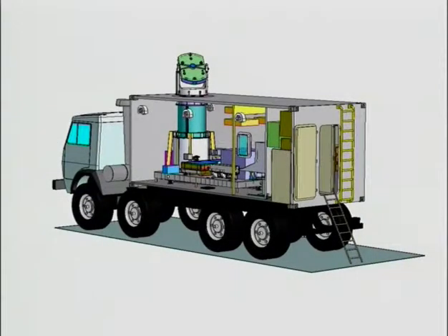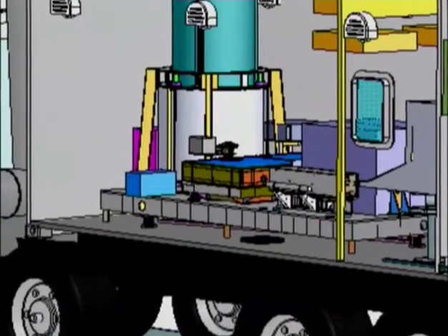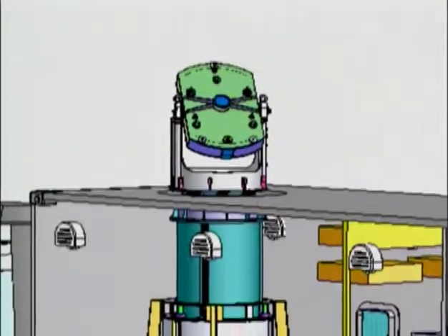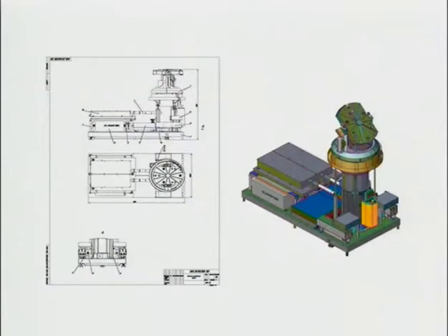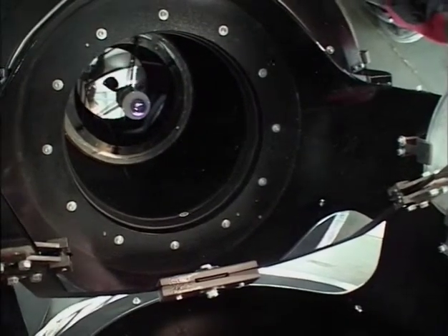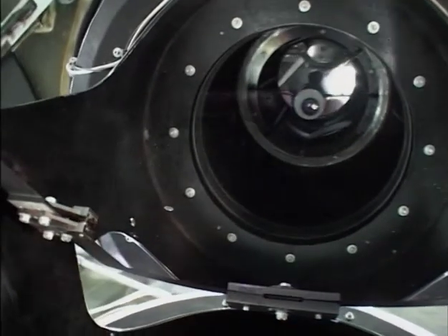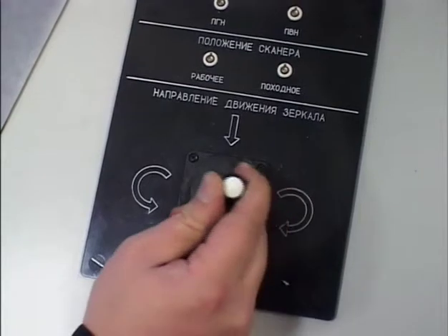Monitoring pulses output and processing a reflected, scattered signal from the atmosphere is provided by the receive-transmit system. The system includes a two-axis scanner telescope, transport optics, light sensors. The receive-transmit system's equipment is mounted onto an optical plate. Rotating scanner with a turning mirror allows monitoring the atmosphere within a wide spatial range, ±180 in azimuth and ±15 in elevation.